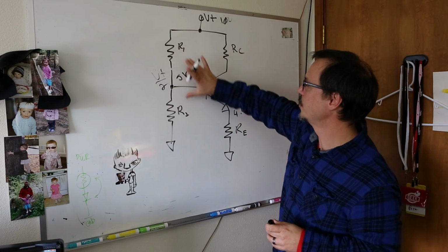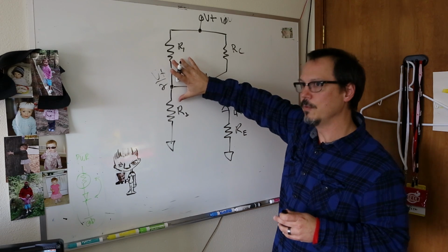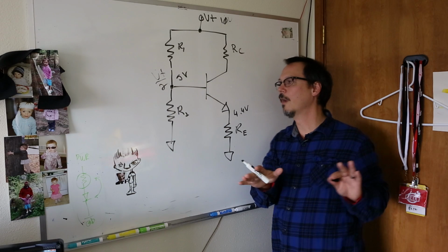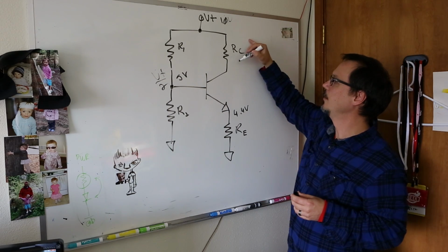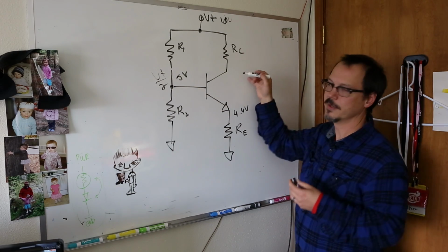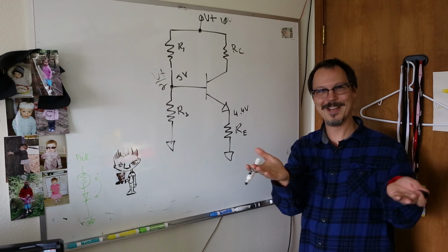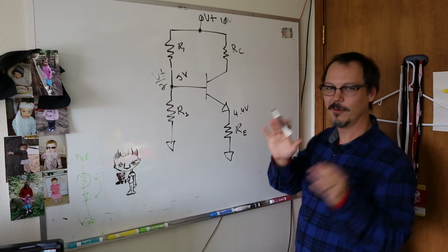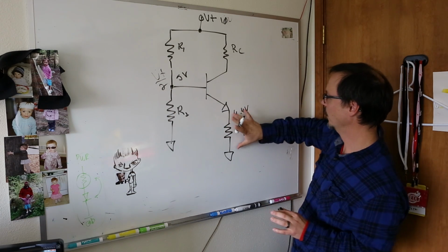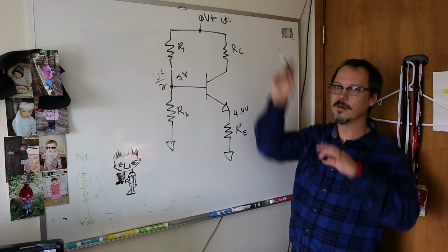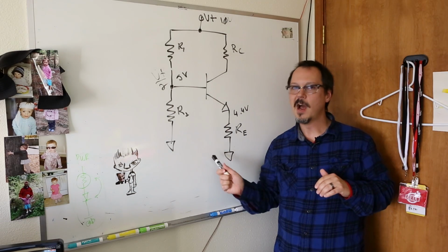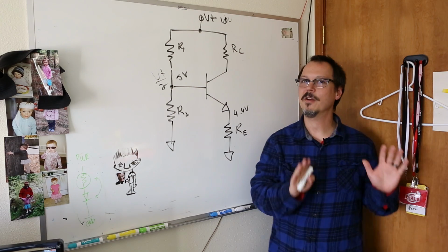And then these are just a resistor divider, but their values can become critical depending on the application. And this will become clearer as I go. This guy is typically used for setting up an operating point or limiting currents through this thing. And that'll become clearer again. I keep saying that, right? General concepts right now. The first thing you want to do is turn it on with regard to DC. And this is what we're doing. We set up our divider, we figure out our voltage here, we figure out how much current is here, and these are all going to be iterative. When you're working with stuff like this, it's not an exact science, all right? This is an iterative process.